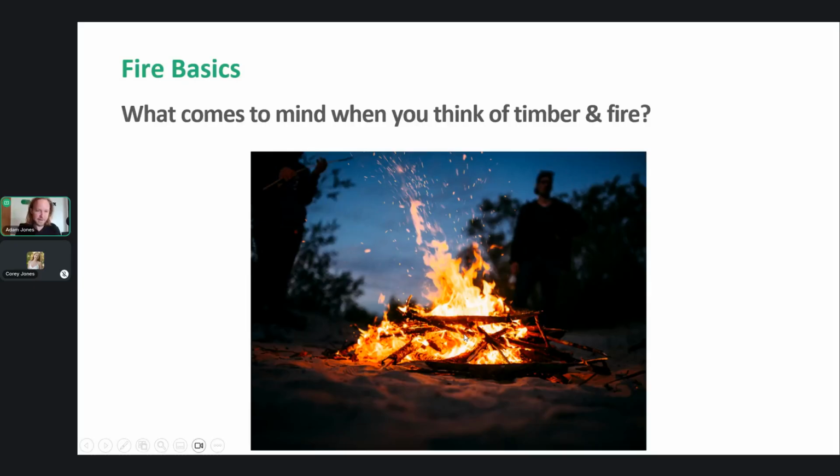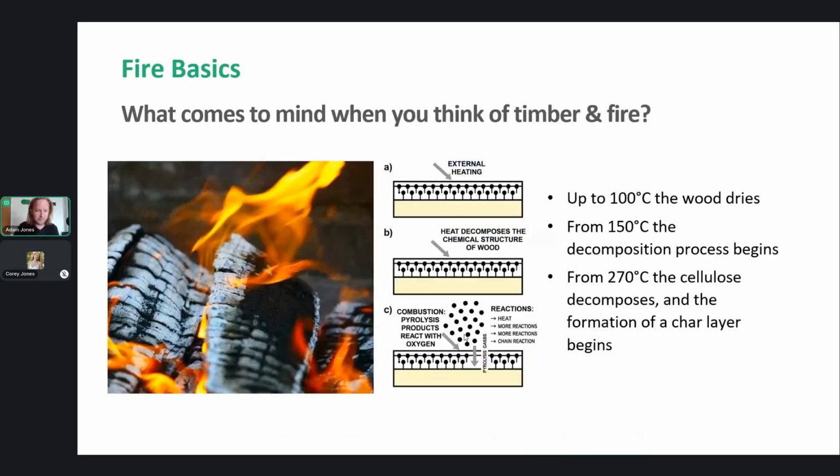And if you think about our buildings, like you might have a beam re-radiating onto a wall, or a wall onto a floor, and multiple exposed members have that interaction on top of each other. But there are certain ways you can design that out and make self-extinguishment more likely. So if you look at the chemical reaction, what happens is as you heat up the wood, there's a certain period where it dries up, so the moisture content is completely eliminated from the timber. Funnily enough, that is a piece of variability that's in fire tests as well that not always covered.